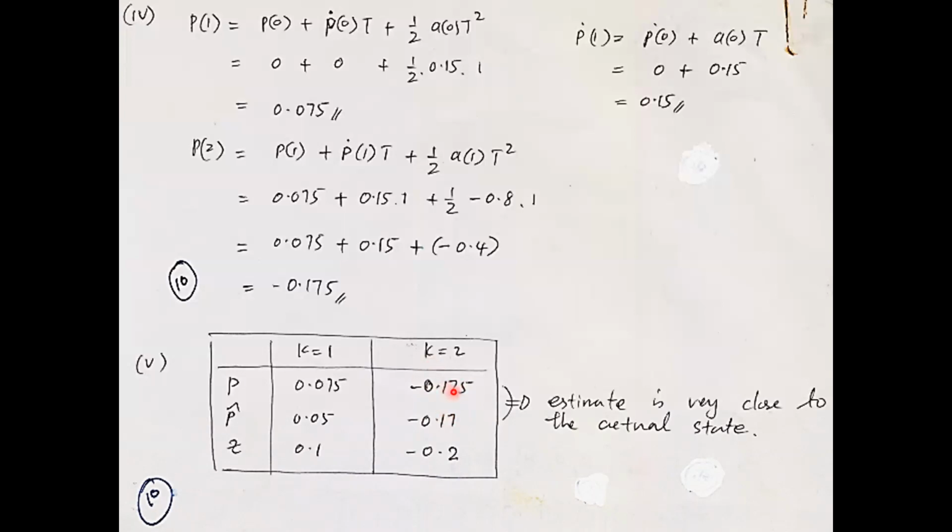That's how powerful the Kalman filter is in predicting a true value. Remember, this true value includes the unmodeled dynamics. Not only the standard state extrapolation or state transition, but there is this anomaly that happens and is not modeled. So there is some sort of dynamics in the process that is not modeled, and the Kalman filter captures that.